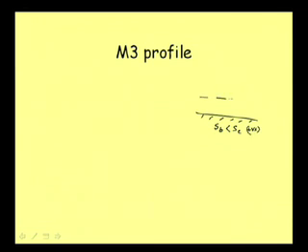As explained already, this is CDL and this is NDL, and the profile here is lying in this portion. Right now, I do not want to say that it is rising or falling, but it is a profile here, and then the depth here is Y, the critical depth line up to the critical depth line is YC, and the depth here is say YN.